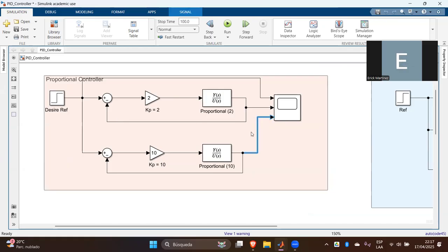Basically, you can observe here that I place again the same transfer function, okay? That is basically the transfer function of this spring mass damper system, but I have already placed a controller, okay? In particular, I am only using the proportional action, okay? And I am using this cable to simulate the presence of a sensor in which I am measuring the position of this spring mass damper system, and I have the desired value, okay, or the desired reference.